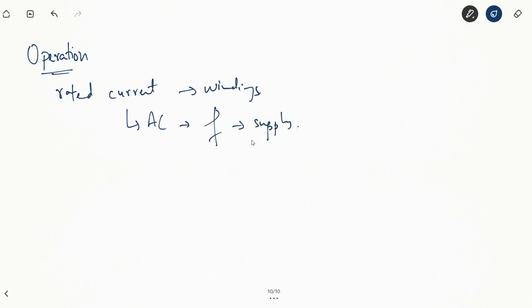So our AC current is alternating through the windings at the same frequency as that of the supply voltage. Now this core will act as the electromagnet that we have already said. It will attract the reeds. So the reeds will start vibrating with respect to the electromagnet. Now the rate of this vibration will depend upon I square.